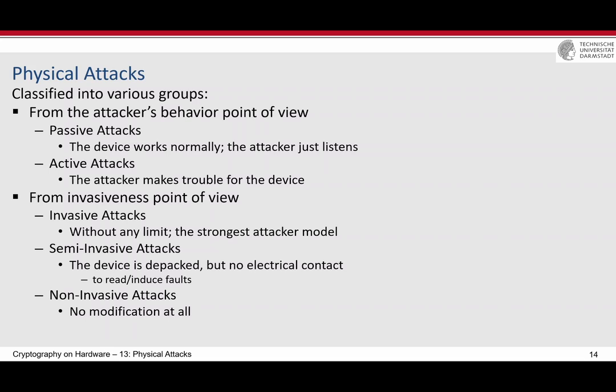Then you depackage it and can reach, for example, the silicon of the device, exactly the gates and the transistors, but you do not make any electrical contact. Now, for example, with some laser beams, you can watch or observe it, or you can change it. And invasive attacks mean that you don't have any limit. Just open it as you want, change anything that you want, place the probe, have some electrical contact with the device without any limit.